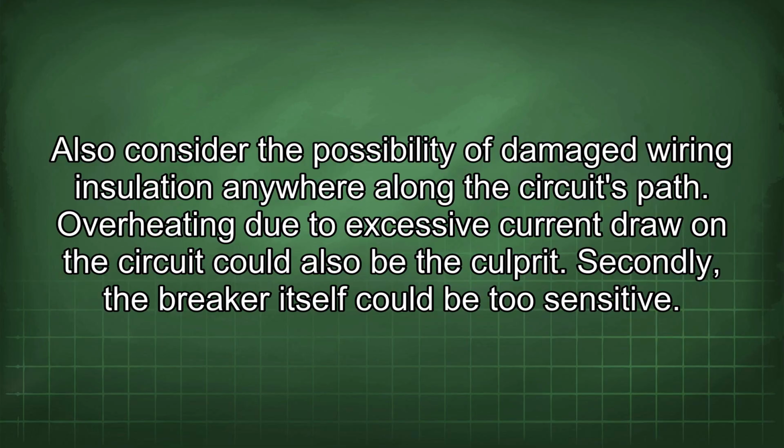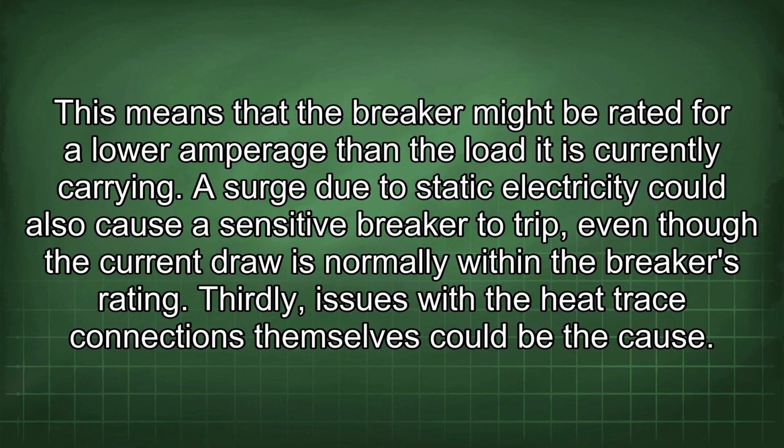Secondly, the breaker itself could be too sensitive. This means that the breaker might be rated for a lower amperage than the load it is currently carrying. A surge due to static electricity could also cause a sensitive breaker to trip, even though the current draw is normally within the breaker's rating.